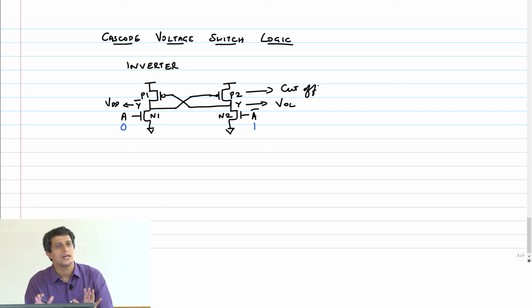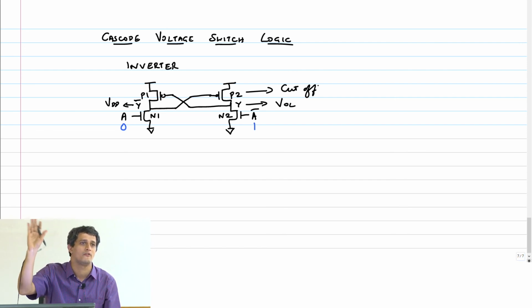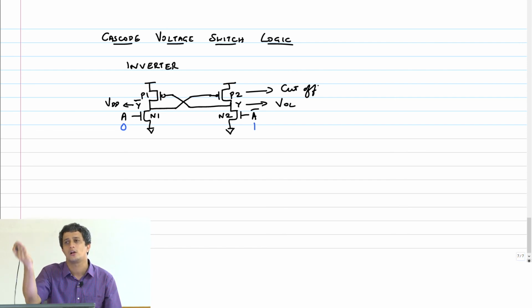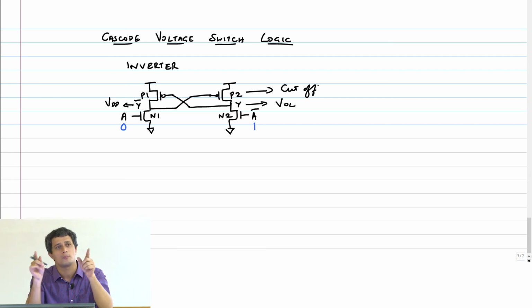So this is clearly a case where it's like a pseudo NMOS transistor, logical effort is low. Note very importantly, my input A or A bar is still connected only to the NMOS transistor. They are not connected to that cross coupled stack anywhere. If it is connected, then the logical effort will go up. That's a problem, right? So this cross coupling is happening only between output and this.